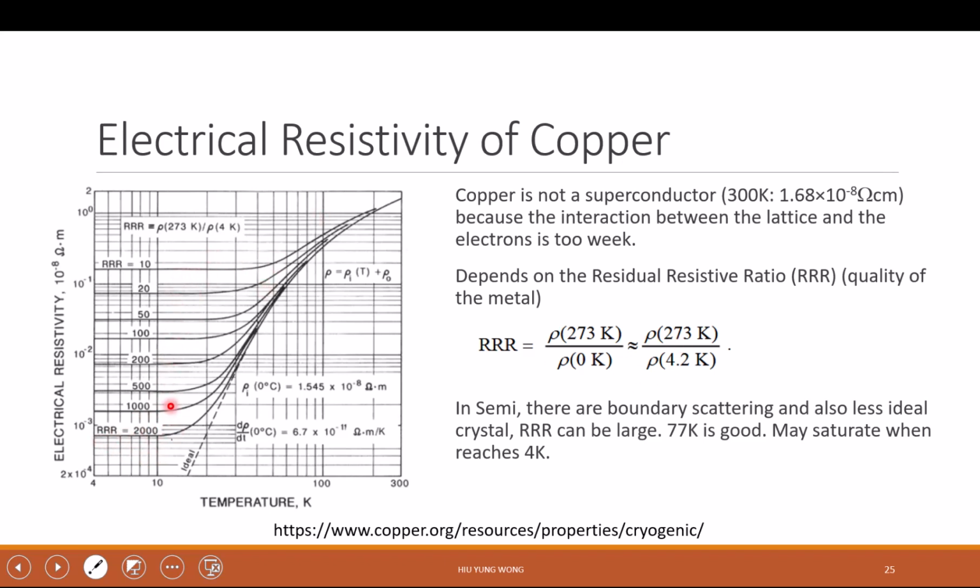But for different quality, the reason they have different saturation levels is because you have different types of quality. You remember when you go to very low temperature, you don't have the phonon scattering anymore. Your atoms are not vibrating as much, so your electron can pass through easily, right? Then you thought that you will have a very low resistivity. But unfortunately, now the impurities, if you don't have a good quality, dominate.